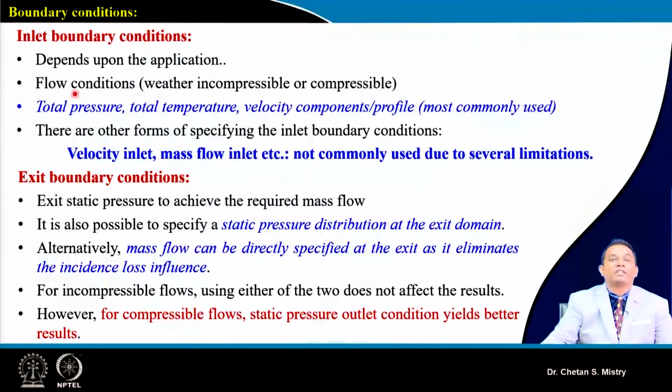When we are considering a subsonic compressor versus a transonic compressor, that is what differentiates compressible flow and incompressible flow. So total pressure, total temperature, velocity component or profile is what is most widely used as the entry boundary condition, or inlet boundary condition.